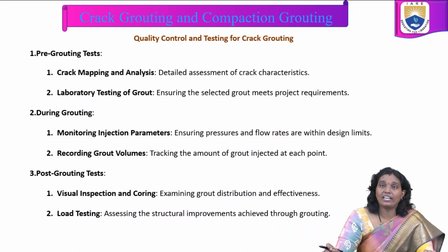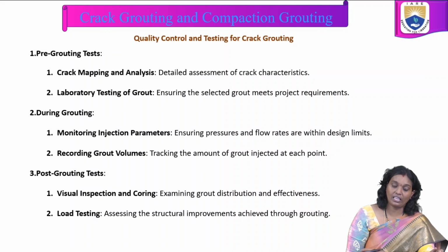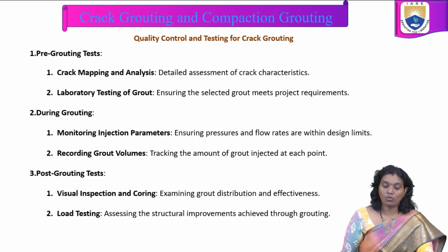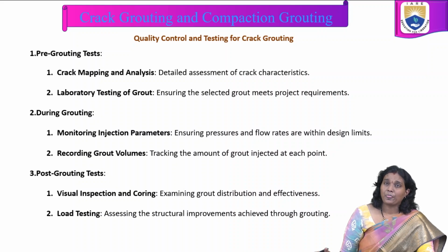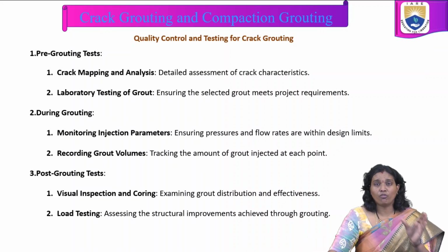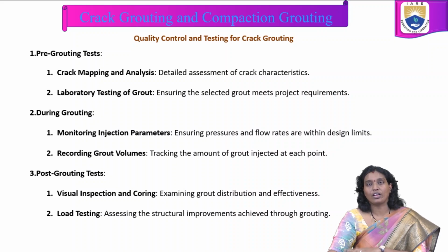Coming to the quality control and testing for crack grouting: pre-grouting test, during grouting, post-grouting. Coming to the pre-grouting, we are going to consider crack mapping and analysis, and laboratory tests of those grouts. During the grouting, we are going to monitor the injection parameters as well as record grout volumes. After grouting, post-grouting tests, visual inspection and coring, load testing we are conducting for understanding the quality of the crack grouting, and whether what we have chosen is in line or not, we are going to understand.